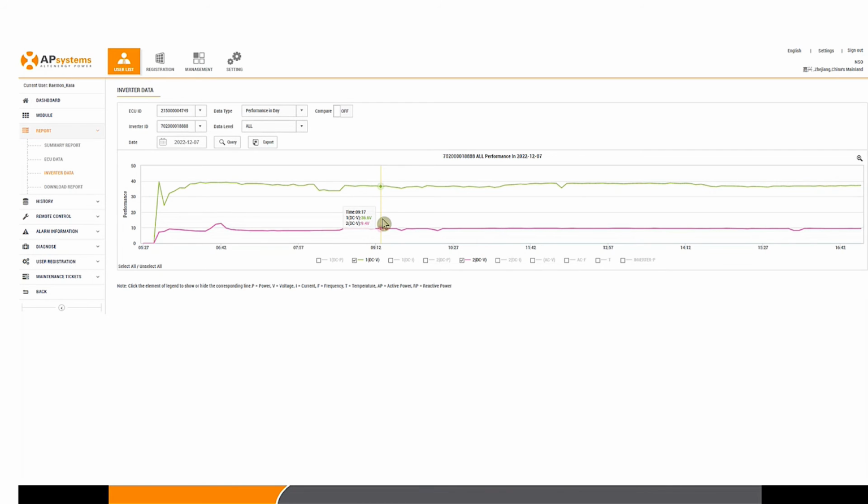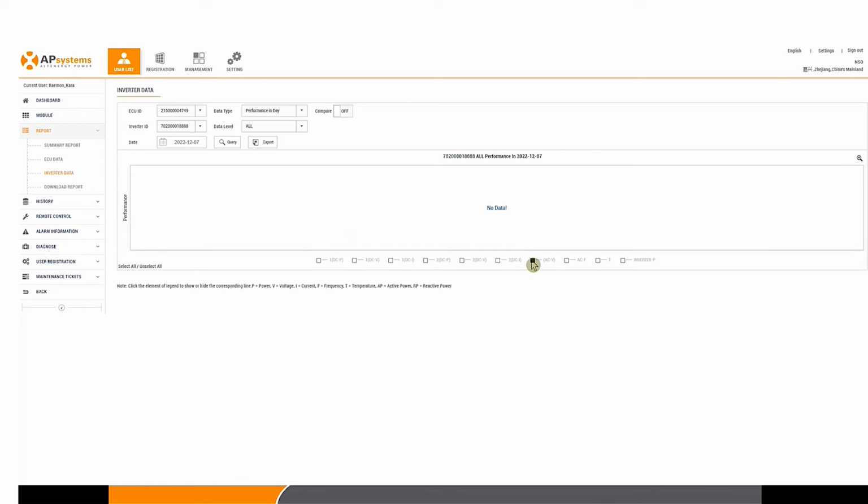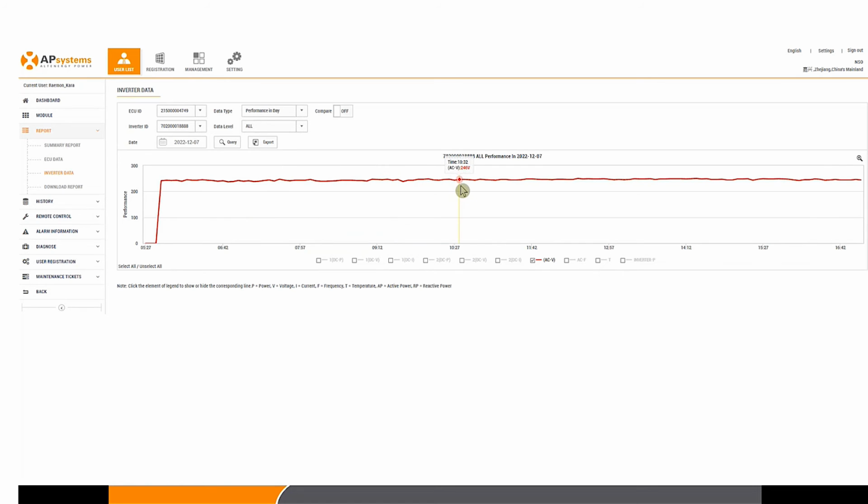And so someone has to go back out and replug the panels, or they have to check the paperwork whether they actually did install 2 panels on this inverter. So this is one really common thing you can troubleshoot. See how it says about 9, 8? That's a really telltale sign of a channel not plugged in or not in use. You can also double check everything by looking at the grid voltage. It's good. See, it's hitting around 240. It's a bit high, but that's normal. So it's clearly a channel that's not plugged in. I'll show you another example.